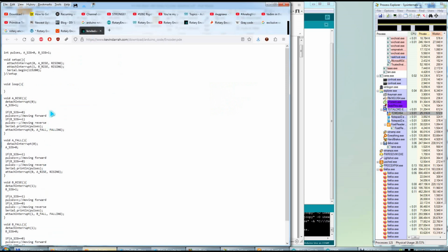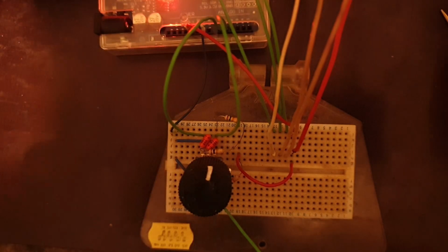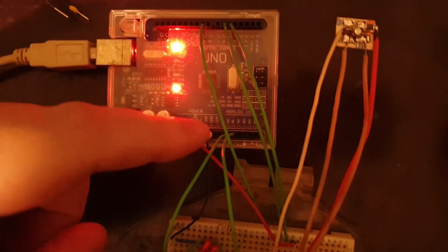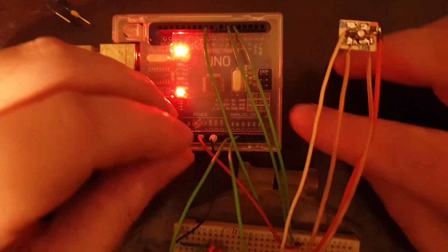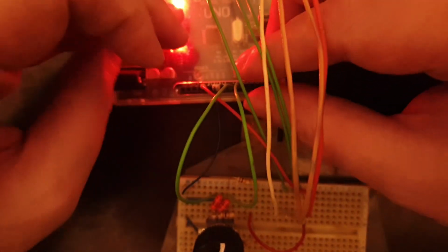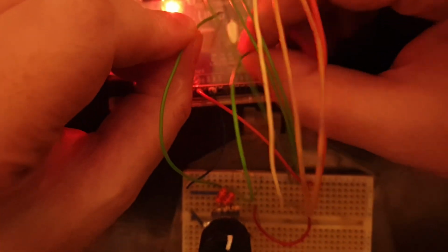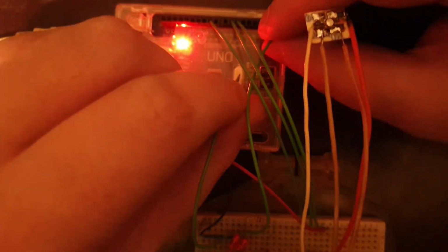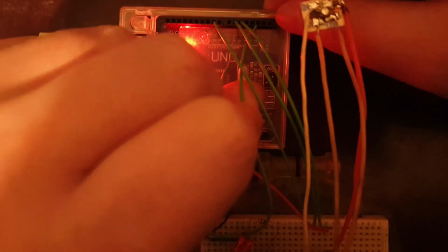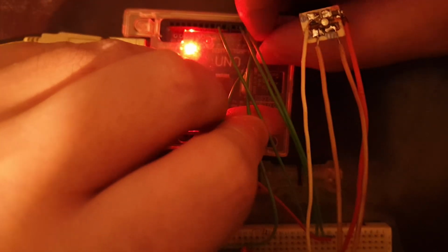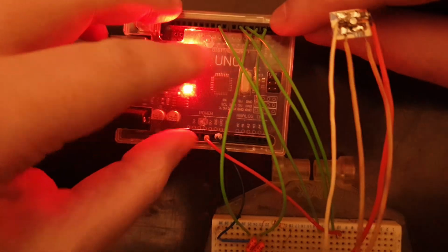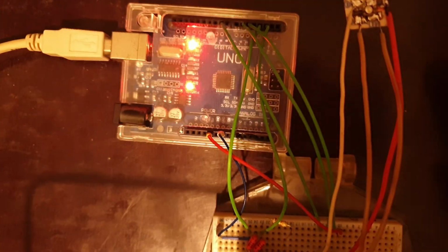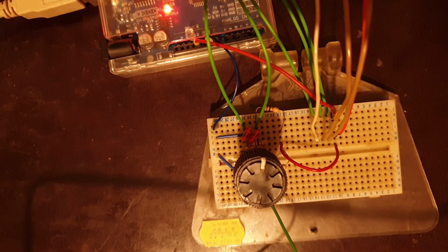It didn't work. I mean, it did work on my side, but it worked with fantastic errors, very nasty errors. So for this one, I have to change from these pins here to there, where it is using some specific interrupt pins. So I have to take the A and B wires and move them to the other side. So it's pin 2, it's 0, 1, and 2. That's how it's working. And on this one, 0, 1, 2, 3. Pins 2 and 3 are for the A and B pins, they are the interrupt pins.